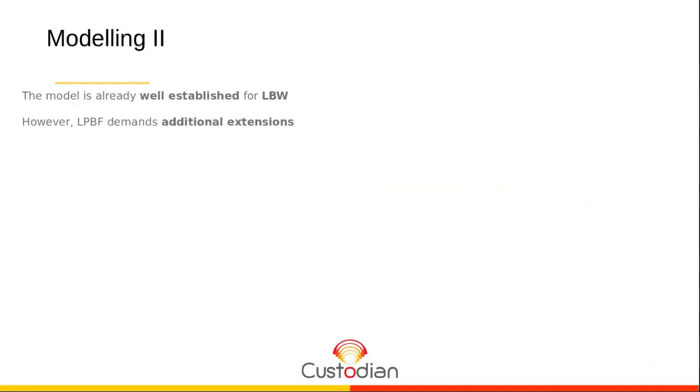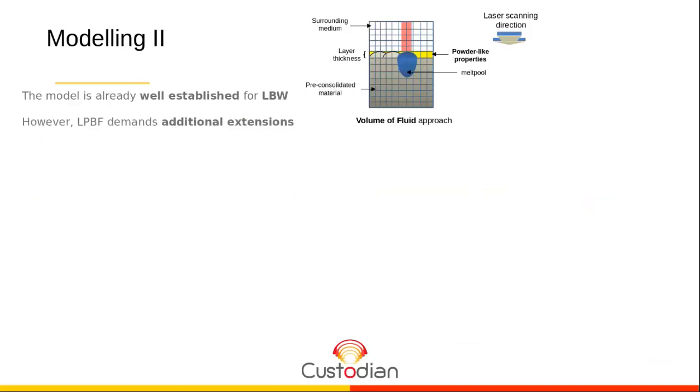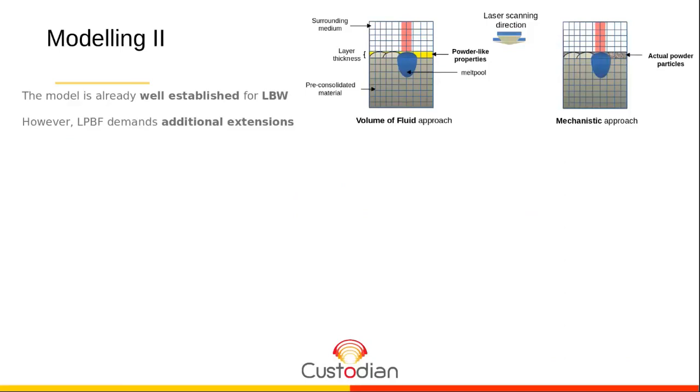In the case of powder-based additive manufacturing, laser powder bed fusion, it is a bit different, the story. So we are following two different approaches. Ideally, I would rather prefer the mechanistic approach, because it resembles more accurately the mechanisms that the real process has. Like having a block and a powder bed or layer of a certain thickness composed by actual powder particles.